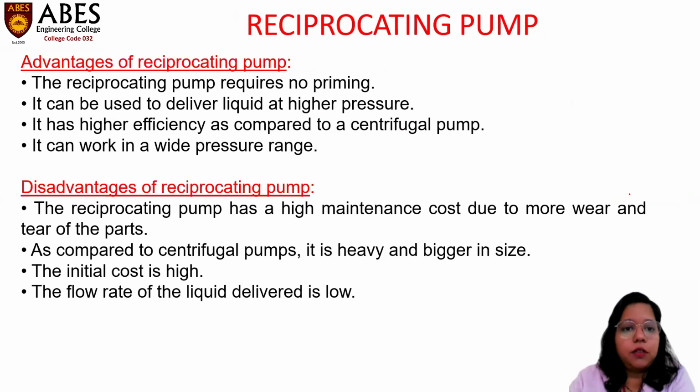These are the advantages of reciprocating pumps. The reciprocating pump requires no priming. It can be used to deliver liquid at higher pressure. It has higher efficiency as compared to a centrifugal pump. It can work in a wide pressure range.